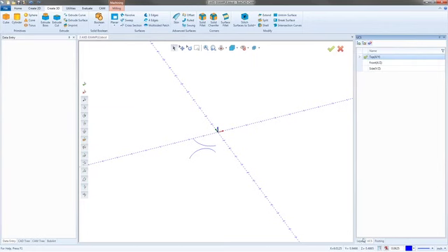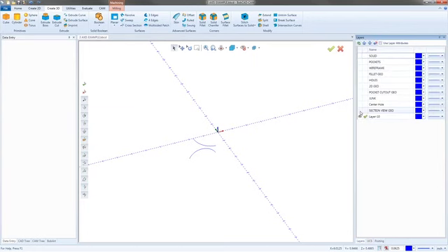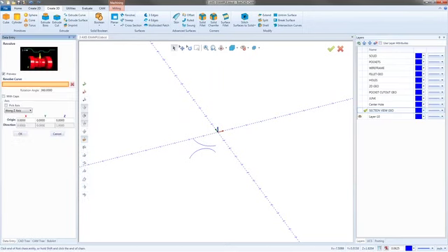So now I can go over here to my layers. I'm going to do one on this layer, one on the other layer. Right here, I'm going to turn on the section view for the top. To create the revolve, I just go to the Create 3D tab and then go to Revolve. From here, it will default to 180 degrees. I've already done this with this part open. I was playing around with this a lot before you guys got here. So I've already changed mine to 360, but normally it'd be at 180. You would just change it to 360.